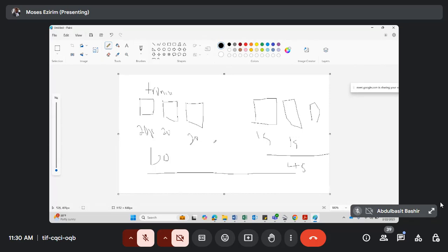Now, let me tell you this. During peak sun hour, when the energy from the sun is too much, this PV will definitely go to zero. Everything will go to zero. Do you understand that? The yield will go to zero. So at the end, I'm just using from the battery. Do you think the installation is efficient? No, it is not. Because during the day, I'm meant to be using the energy from the solar. It shouldn't shut down. Because once it shuts down, I'm not using the energy from the sun, which is free.